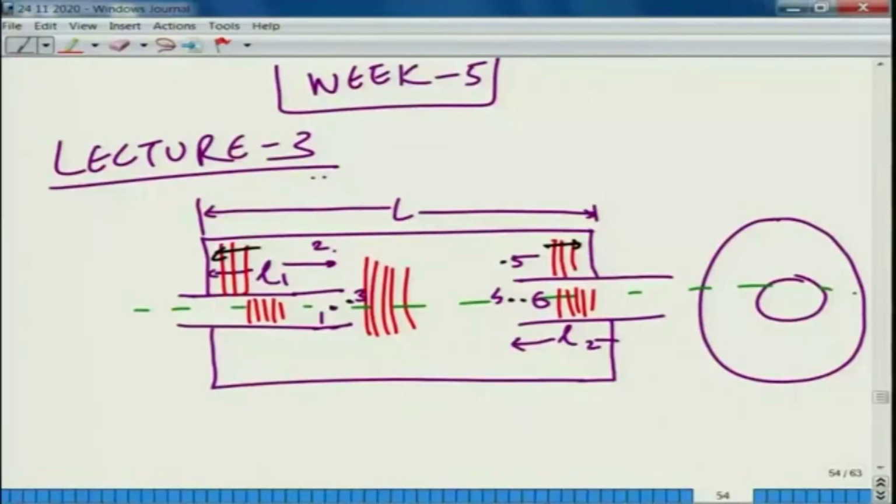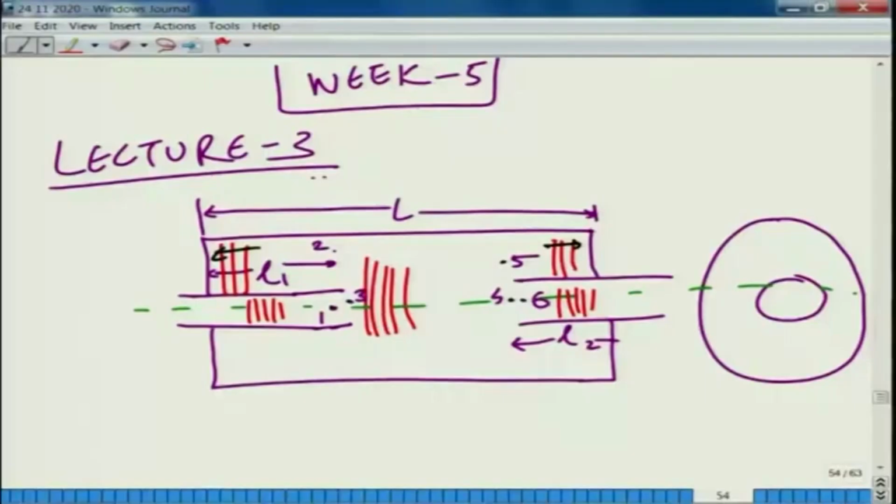For the transmission loss parametric studies, it is very interesting to see how this simple tuning can actually help us to increase the overall performance. For getting a feel for that, we will probably have to go to MATLAB. So, in the later parts of this lecture, we will do some hands-on practical examples by taking realistic lengths and cross dimensions of the diameter d and things like that. But before we do that, let us derive the transfer matrix.